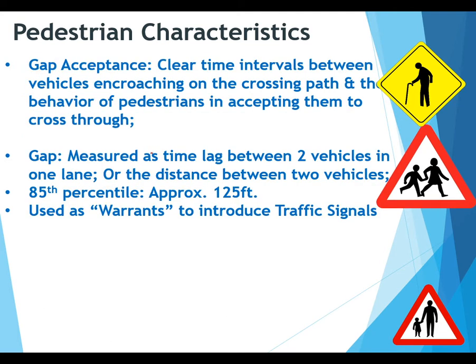Okay guys, one new term we'll be using a lot, especially when we design for signals, is called gap acceptance. Gap acceptance is simply what happens when you want to cross the road and there is no signal. When we want to cross, we look at the cars and find a gap. If we accept this gap, meaning I can cross while this gap is there, I go ahead and cross the road.